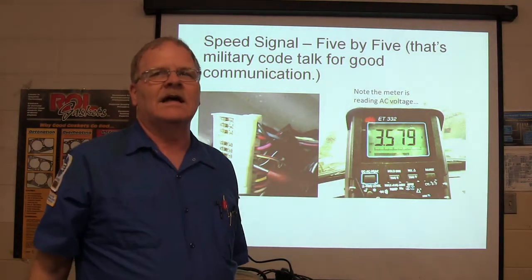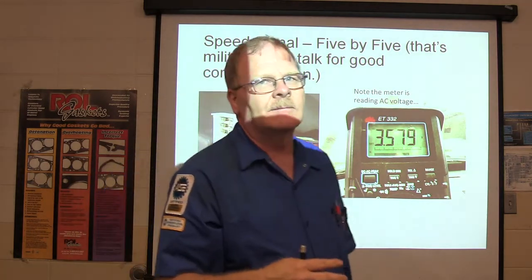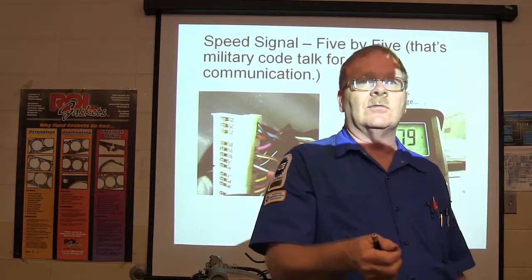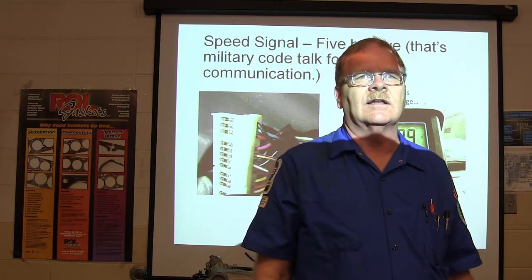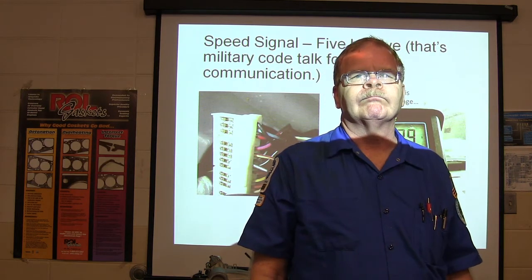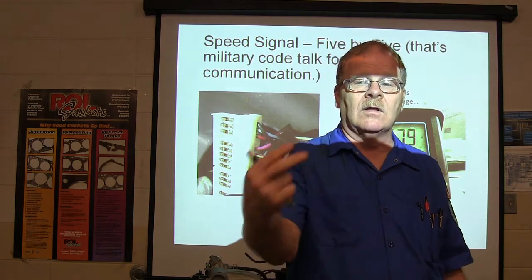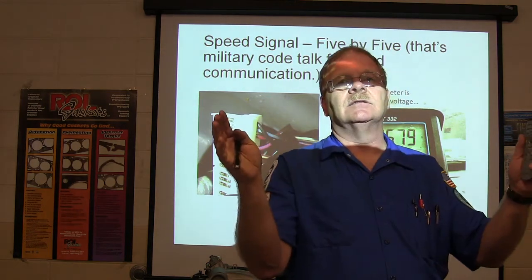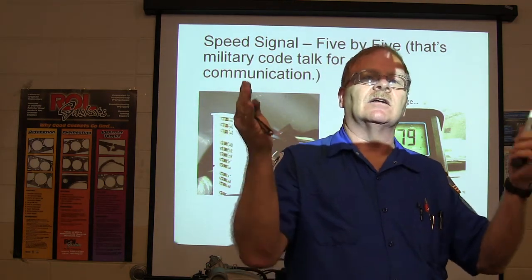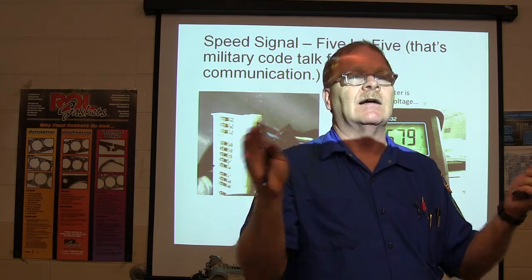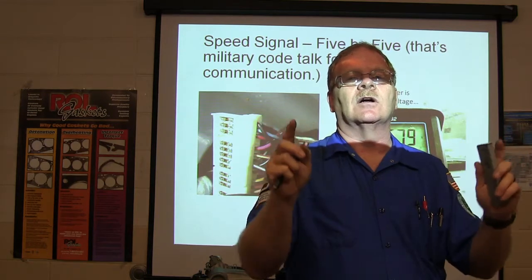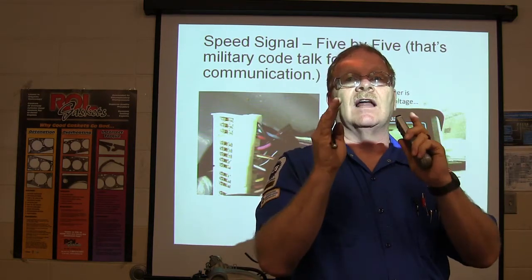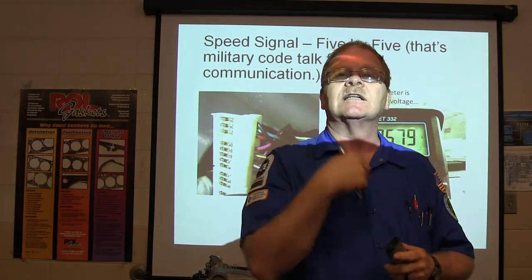Okay, so what are you thinking now? If I'm getting a signal all the way to the cluster, and I've actually got good communication on my scan tool, and I hadn't found any ground problem yet, what do you think is my problem? If the signal is making it to the box, and the box is not responding to the signal, what does that sound like to you? Everything else is working on the cluster. All the gauges are working, the speedometer is offline, even though it's getting a signal.